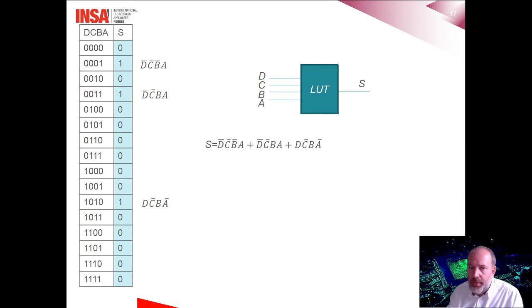The example here shows the implementation of a particular logic function and the corresponding content of the lookup table. Here we have a 4-input lookup table with A, B, C, D as inputs. The lookup table therefore has 16 memory cells to store just a single bit. In the current configuration, we see that only 3 bits have been set to 1.